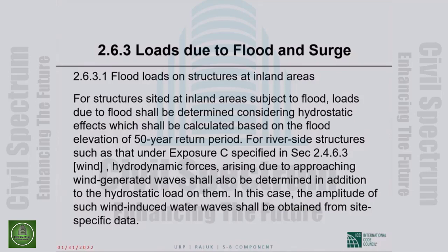So for structures sited at inland areas subject to flood, loads due to flood shall be determined considering hydrostatic effects, which shall be calculated based on the flood elevation of 50-year return period. Okay, that's an understandable sense.